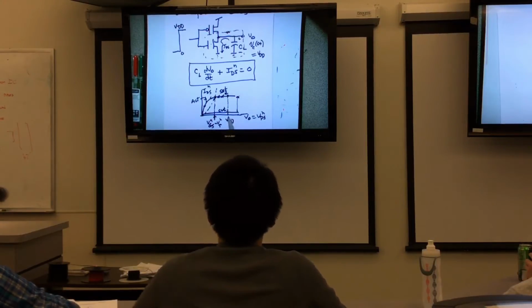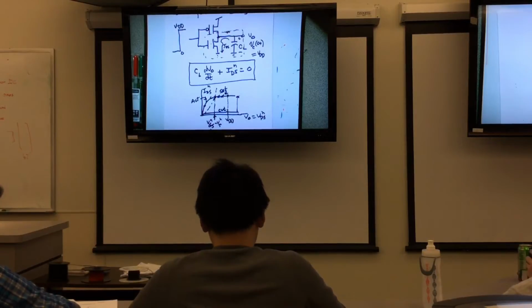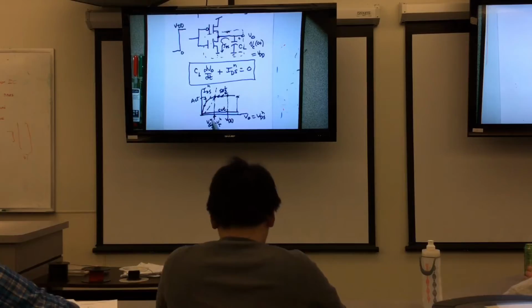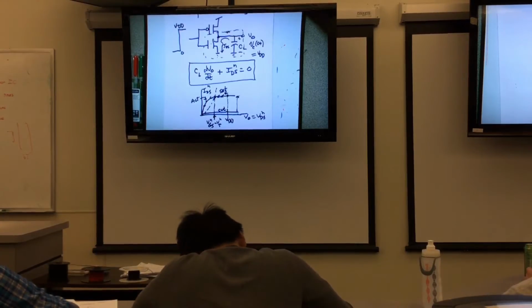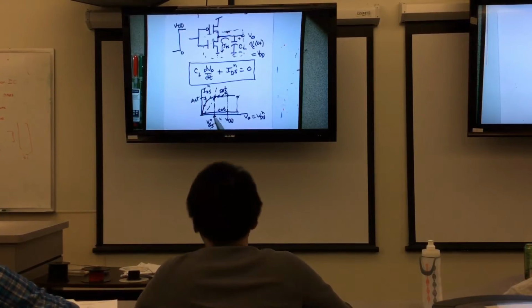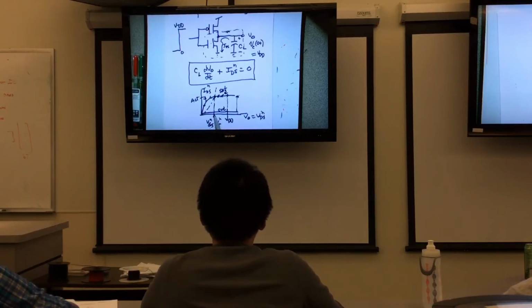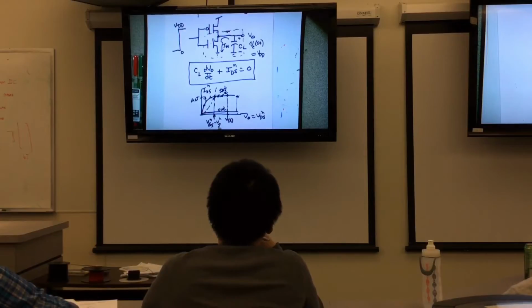Anyway, so this is going to discharge from VDD down to VDD minus the threshold, which means this might be 2/10 of a volt. Maybe 1 volt to 5 volt here that we're doing with our kit. And it's roughly a factor of 5 down from what this is. In more modern structures, we're unable to make the threshold go down, and yet we're trying to keep the voltage going down.